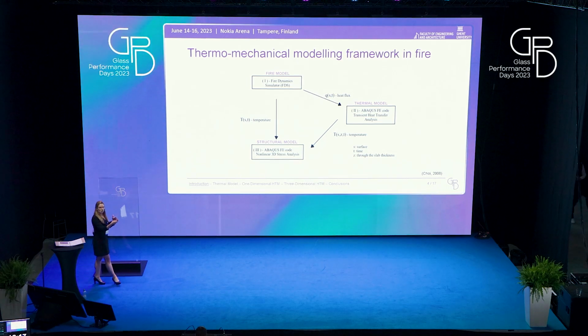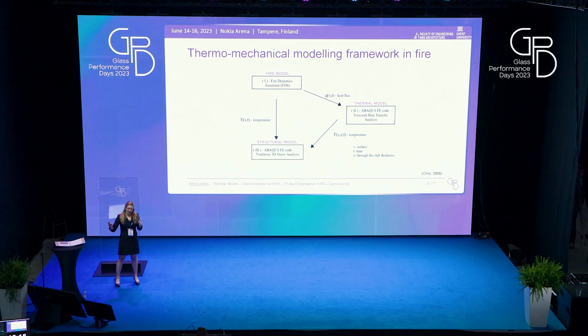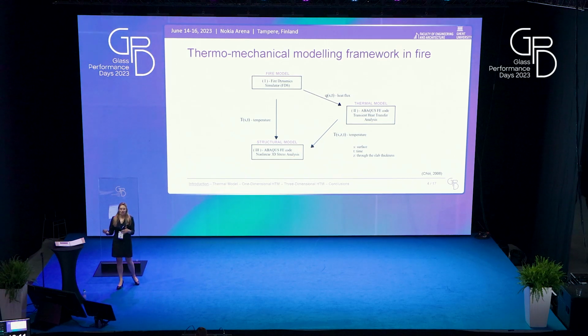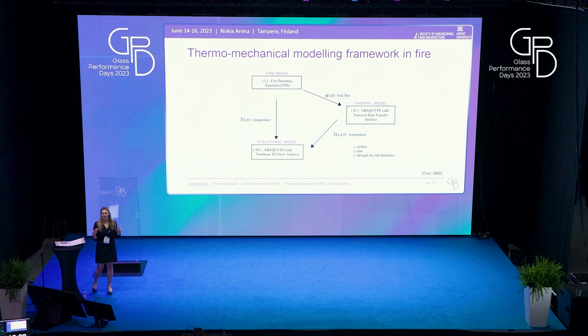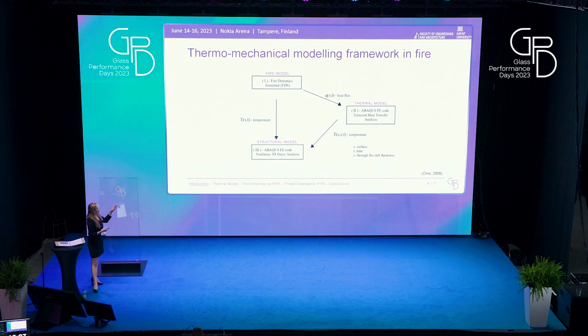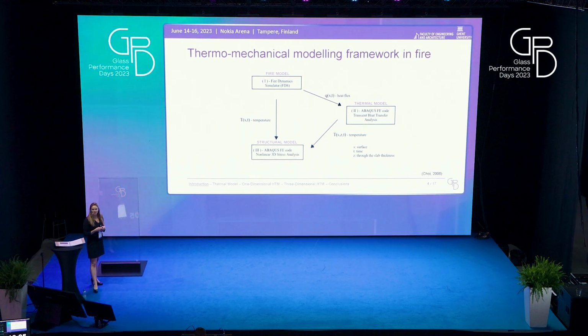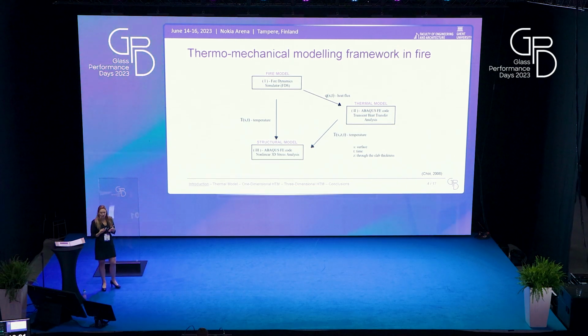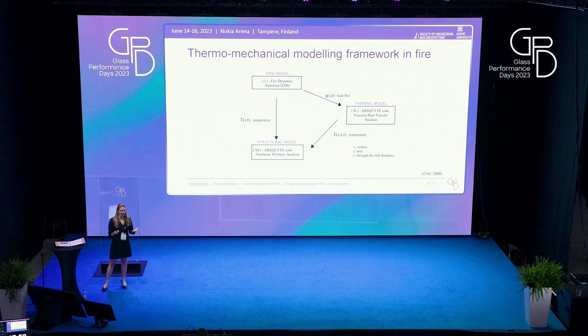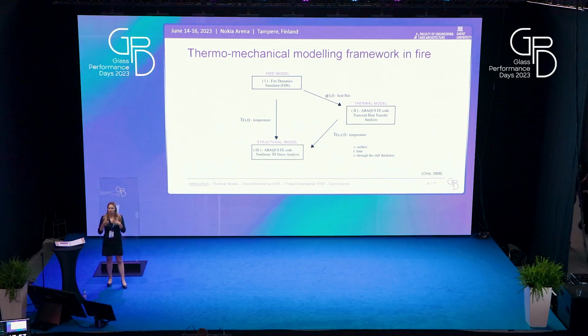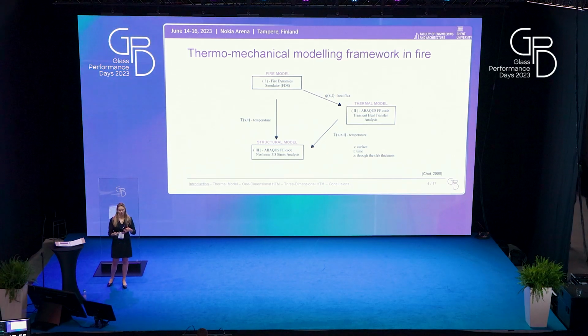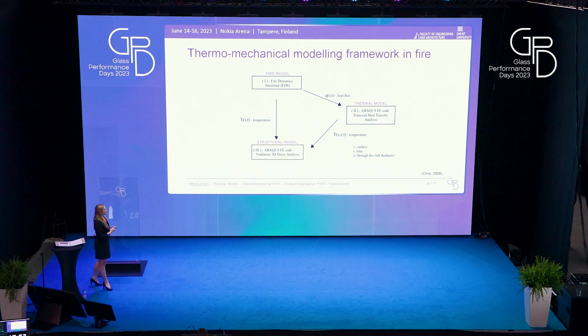Then when you go to the thermal model, you can input the heat fluxes, and you will get the temperature fields in your element, so in time and in space. And then you can input the temperature fields in a structural model, and the structural model will quantify the overall behavior of your element when it's exposed to the combination of thermal loads and mechanical loads. That's basically how it works in general.